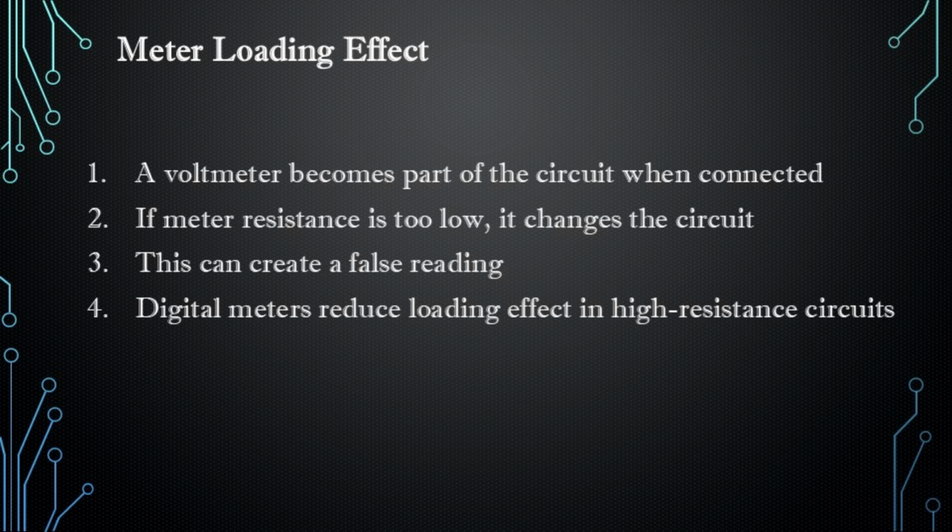Slide 6, meter loading effect. Now we get into one of the most important ideas in the whole presentation, and that is loading effect. When you connect a voltmeter to a circuit, the meter is not just passively watching. It actually becomes part of the circuit. That means the meter itself can influence the circuit being measured.